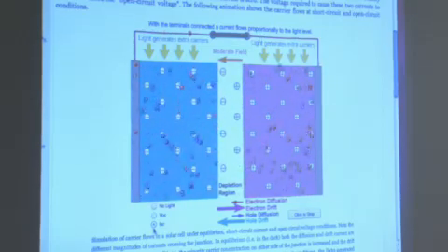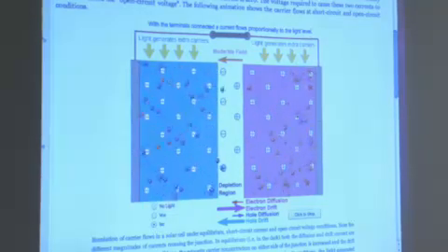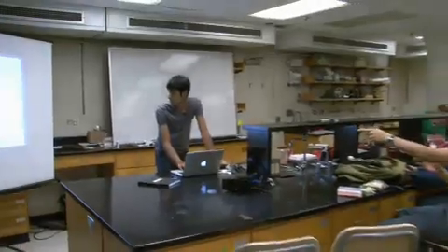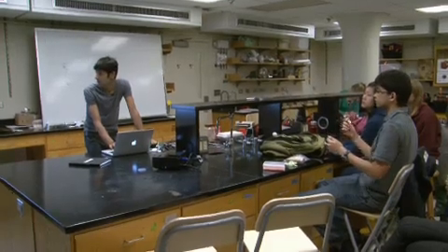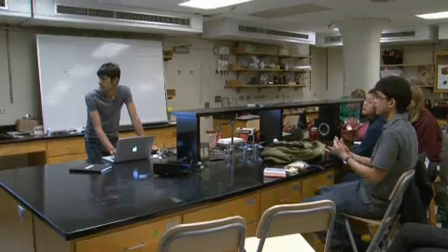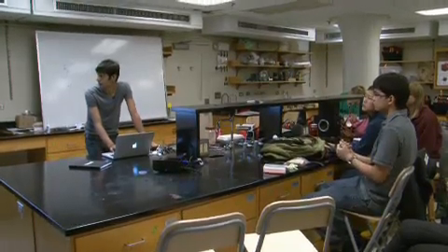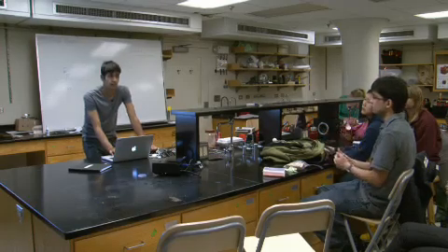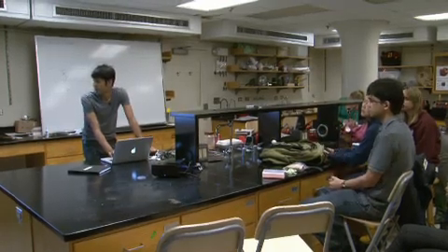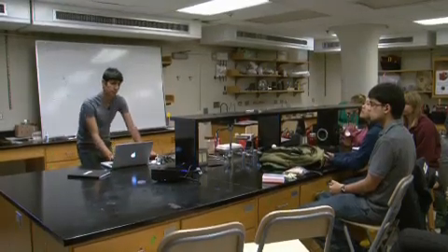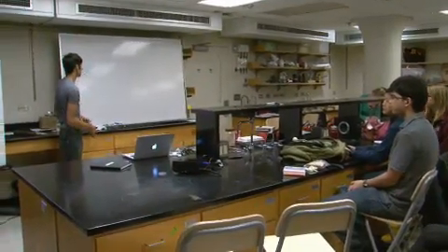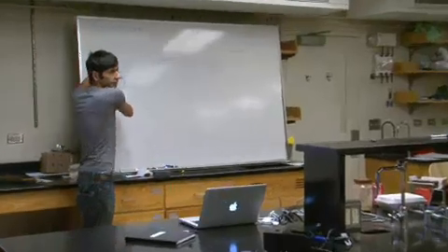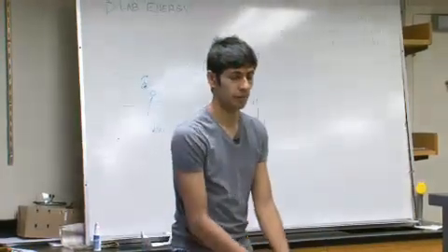I mean, basically I understand the concept. I was just curious whether, in the diagram, in the middle region, the depletion layer, my understanding was that's where the light hit and where the electrons were ejected, and then they would move around. But this diagram doesn't seem to be doing that. Yeah, I'm pretty sure the light excites or creates electron-hole pairs anywhere inside the entire cell, but I can double check and follow up on that as well.